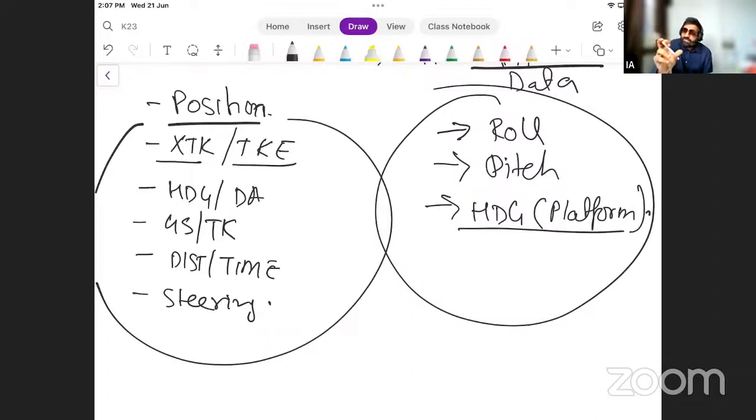Now, what kind of gyro has springs? If you remember the turn and slip indicator, a rate gyro has springs. A rate gyro has a spring to make sure it comes back to its stable position. Your integrating gyroscopes in INS are rate gyros.